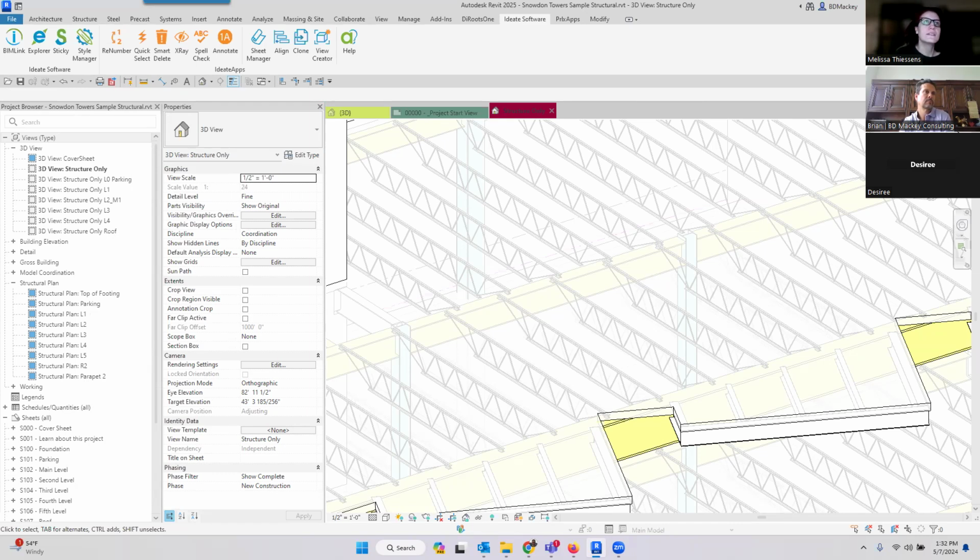All right. What's the best way to copy materials and wall types between projects and keep them the same after changes? Yeah, there's not. Whenever you copy a material, or even edit a material in a family and load that into the project, the first time you do it, it will add that material.